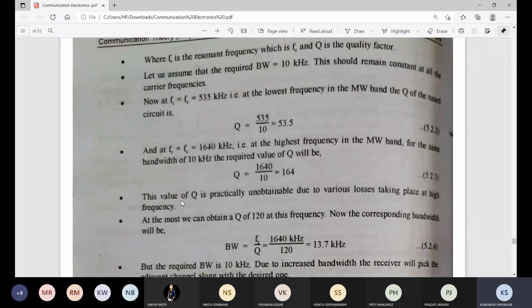So when I have to increase the frequency, our circuit stops amplifying and starts oscillating, and as it starts oscillating, the frequency gets mismatched. As the frequency mismatches, म्हणजेच काय, the resonant frequency FR is not equal to the carrier frequency. Resonant frequency and carrier frequency get mismatched, and due to that, instability is there. Similarly, Q will change, that is the quality factor changes. As the quality factor changes, the bandwidth will change, and we'll see that also.